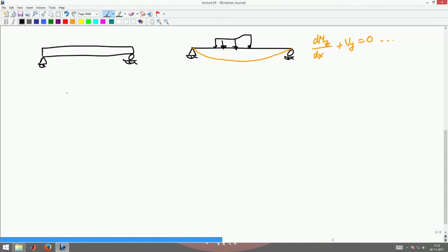engineering mechanics. So when I have a triangular truss like this, which is simply supported at these ends, and I add some loading coming in here, P and Q, you didn't ask the question what is the deformed shape before writing the equilibrium equations. You wrote the equilibrium equation in the undeformed shape and you assumed that the deformed shape will be close to the undeformed shape, that it won't matter significantly.